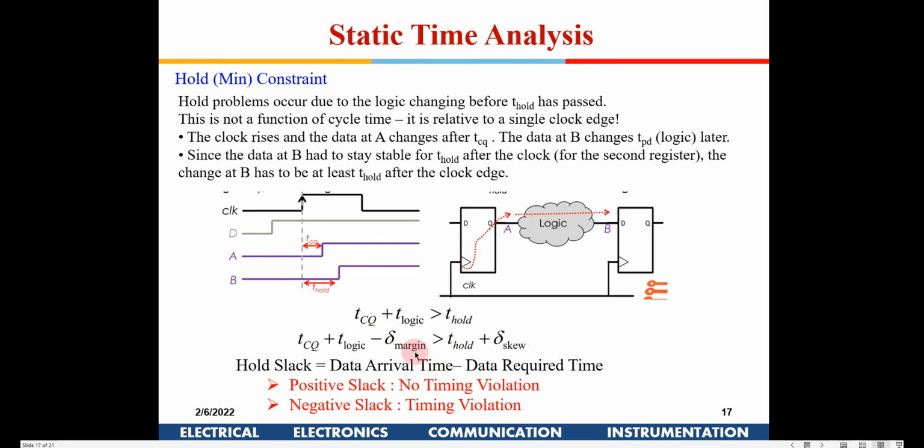In static circuits, those kind of issues generally don't crop up. With aging, you won't have a 0 coming to 1 and so on. But at high frequency applications, if you are keeping these things too tight, then even a few picoseconds, if it is going to capture the next data, you find violations and the entire computation going wrong. So in all these high speed and dynamic applications, these are very critical, and that is the reason we cater for a little bit of margin out here.